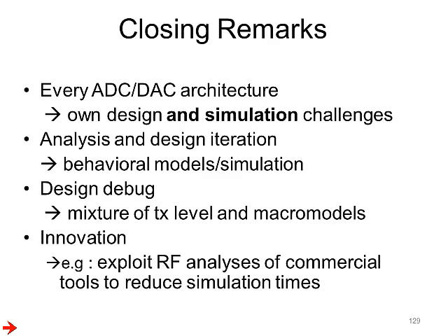So to close, every ADC and DAC has its own design and simulation challenges. It's common to use behavioral models and simulation during analysis and design iteration. During design debug, you might want to use a mixture of transistor level and macro models. And the use of RF analysis is actually a very nice way of reducing simulation time in many converters.